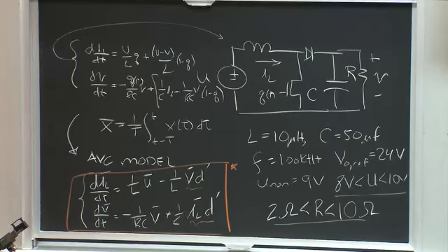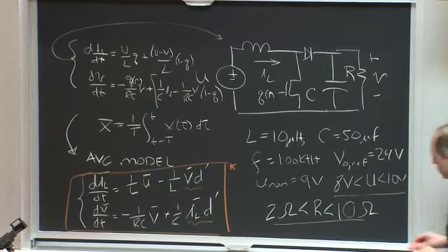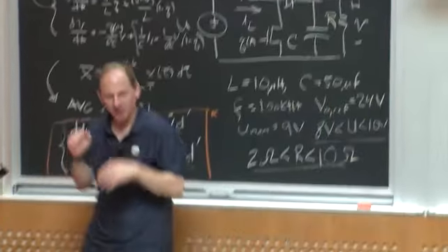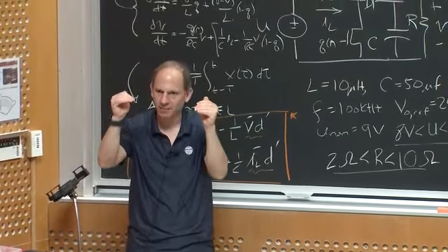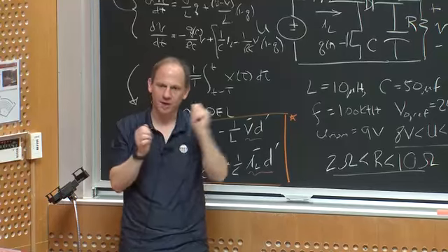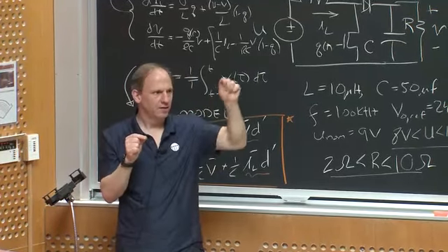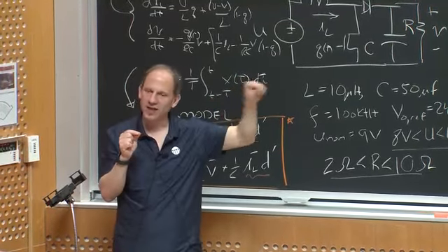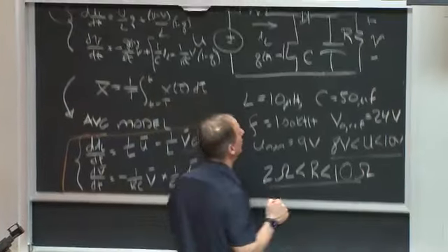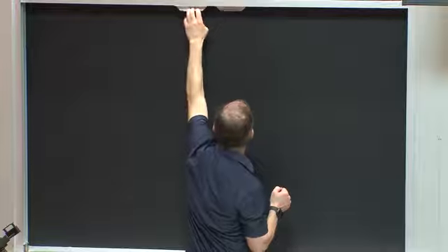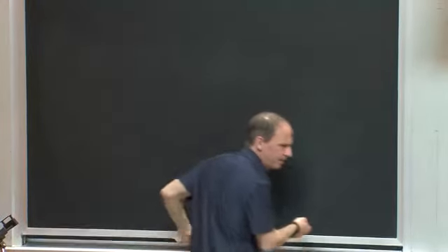We don't like that. We want a way around it. So what do we do? We linearize. And we said what we can do is we can say, suppose this converter is operating at some point, and all I want to know is if I move it a little bit away from that point, how will the response wiggle? I perturb the input just a tiny bit, the output perturbation in the states and the output, maybe that looks close to linear, right? So we went through our linearization process, which we did last time. And here's the result we got.